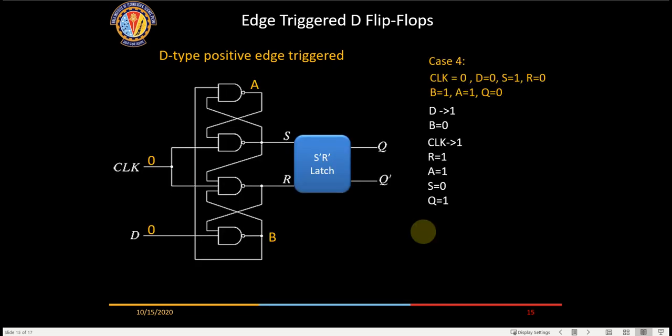Here we don't have an option to set S and R, right? We are not giving any input to S and R. No, we can give, it has to be a 3 input AND gate here, with R and S. So usually in a flip-flop, do we have a clear and reset, sir? Yeah, it will be there. Definitely it will be there. At least a reset will be there for sure. Set may or may not be there in some ICs, but when we do VLSI design at transistor level, we ensure that both S and R are there.